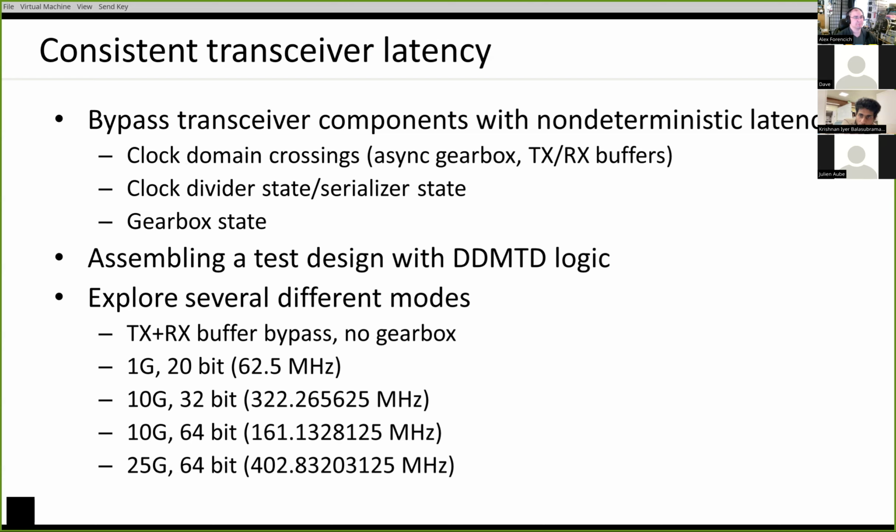But I guess you are right, newer transceivers are better at reporting the actual state rather than you needing to kind of randomly force them into a specific one. Right, right. I think a large part is just bypassing parts of the transceiver that could potentially be a problem, like the async gearbox, that's not going to work. So you bypass it. But once you've bypassed everything that you can bypass, then the question is, is it going to do what you want? And we'll see about that, I guess.